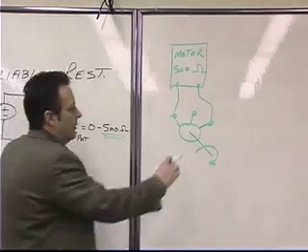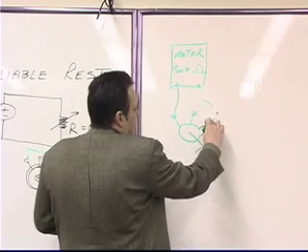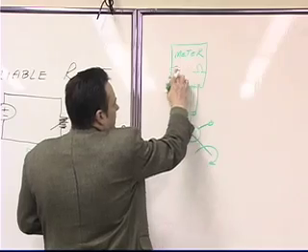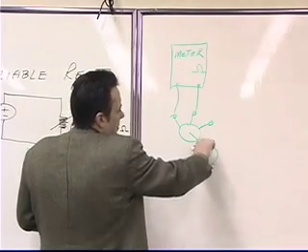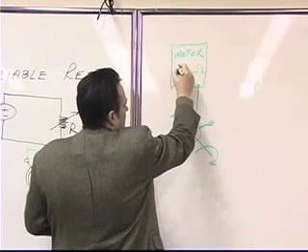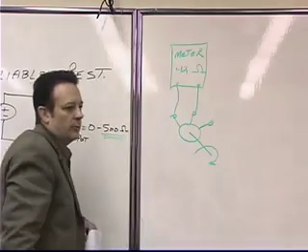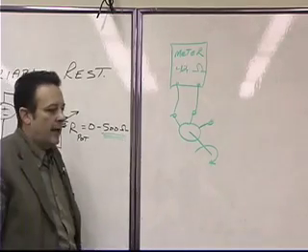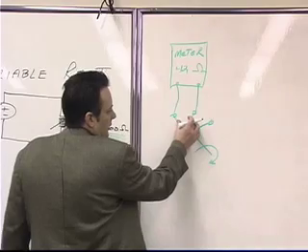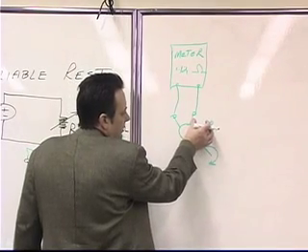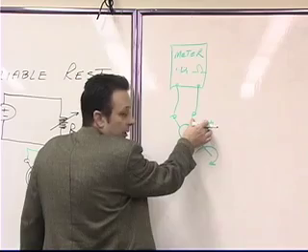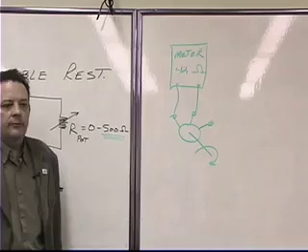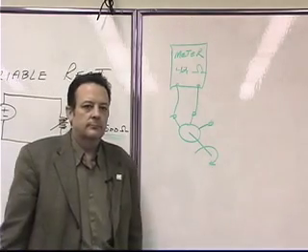If, on the other hand, you take your meter and you connect it here, then as you turn the knob on the potentiometer, this thing will change. 42, 47, 80, 100, whatever. Okay? And the value of resistance here plus the value of resistance here will be equal to the total resistance, or the highest setting of the potentiometer that's possible. Okay?